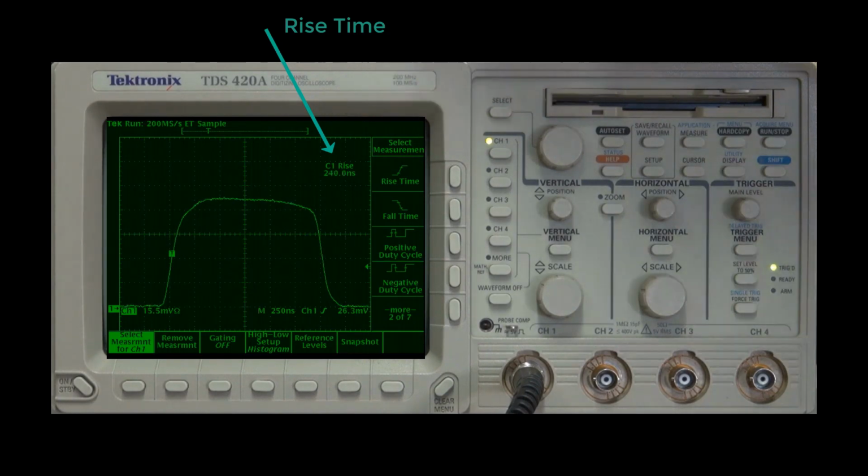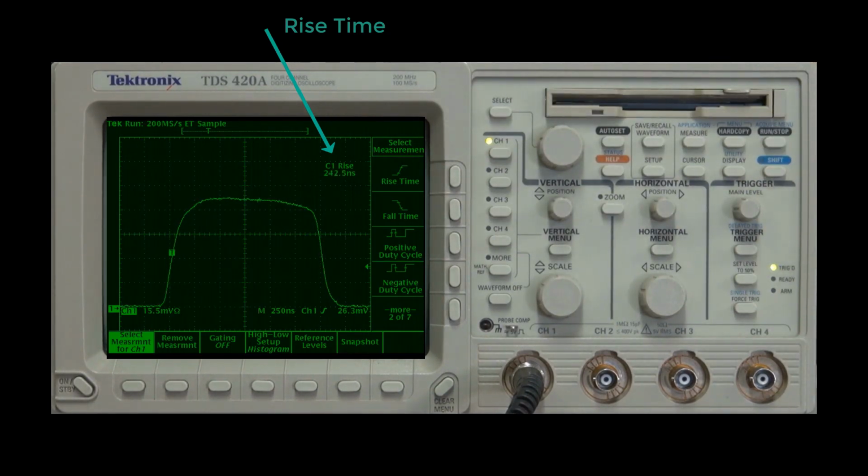As a result of our pre-tune, we're starting out somewhere around 240 nanoseconds. We will insert our tuning tool into cavity 4 and begin tuning to 150 nanoseconds. Notice the waveform is getting larger in amplitude. So if you're doing the manual rise time adjustment, you would have to take that into consideration. And we fine tune it for 150 nanoseconds.